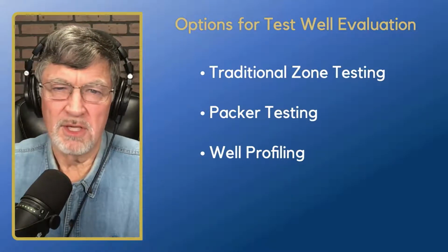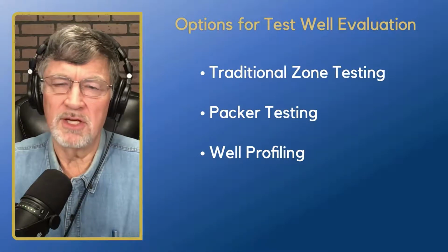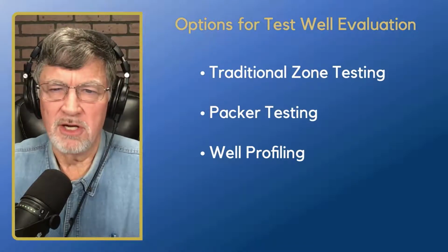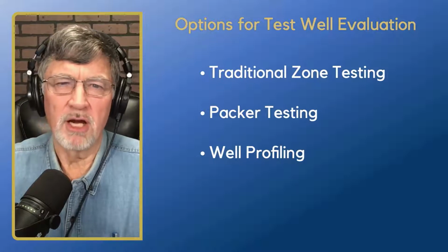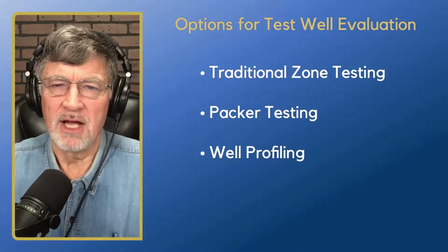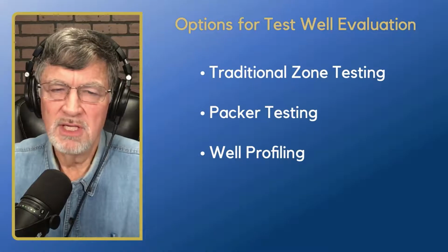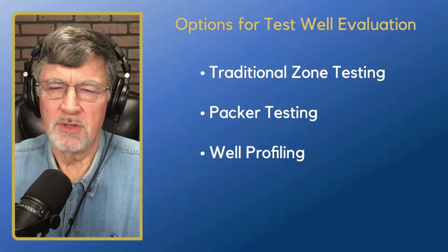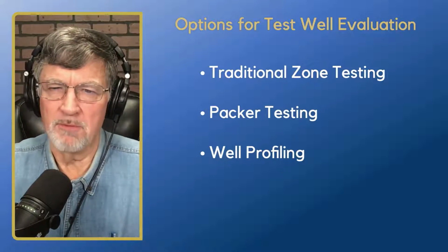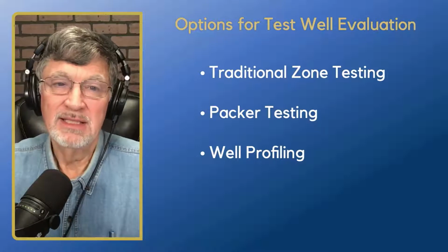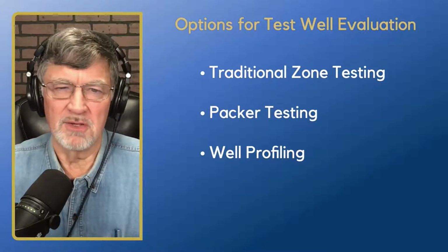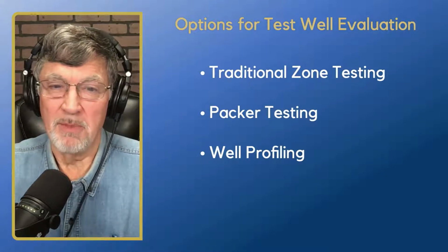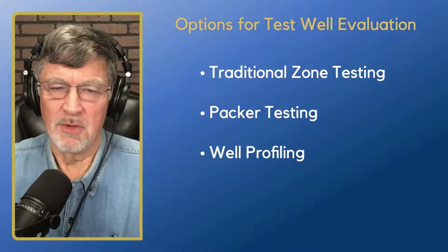Packer testing is something that we'll look at here. Packer testing is using inflatable packers to isolate zones. That generally works best if you have a fractured bedrock aquifer and you're looking at isolating specific fracture zones. If we go into an alluvial well, you really have to trust that well is going to stay open for running those packers in and out, and so I consider it kind of risky, because this straddle packer setup you're going to use can be expensive, and you don't want to bury it down there and lose it and have to go in and drill everything out.